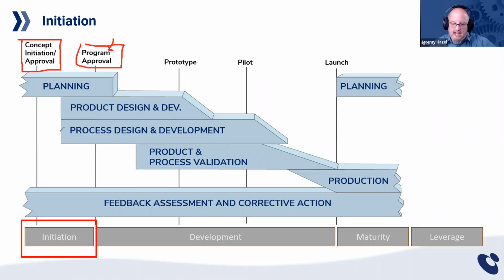A lot of your FMEA development will occur during this phase, because if you are the bushing supplier, you know that you will probably have a boring machine. You will know how many operators you need. You know you will need to have a packaging operation. And if you are a DFMEA expert, you're going to know where that bushing is going to be used. You're going to know exactly how long it has to last. And unless this is your first bushing, you're probably going to pull out some previous designs in which you benchmarked, hey, this is probably what we can provide.